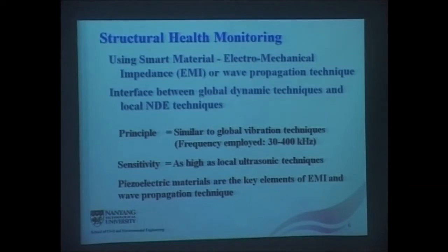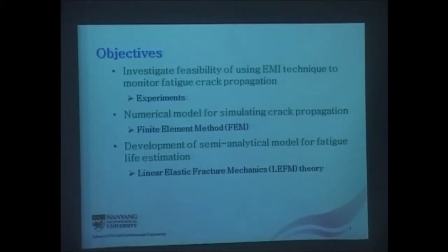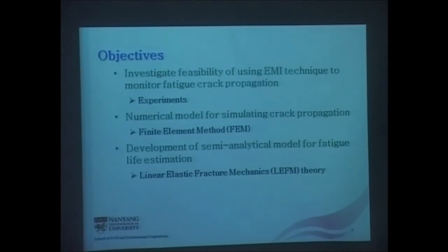And the main materials we use are piezoelectric materials, commonly called PZT materials. For this particular work by one PhD student, you look at the experimental fatigue test, then you look at the FEM method, numerical simulations, then we came out with a semi-analytical model based very much on the LEFM methods.